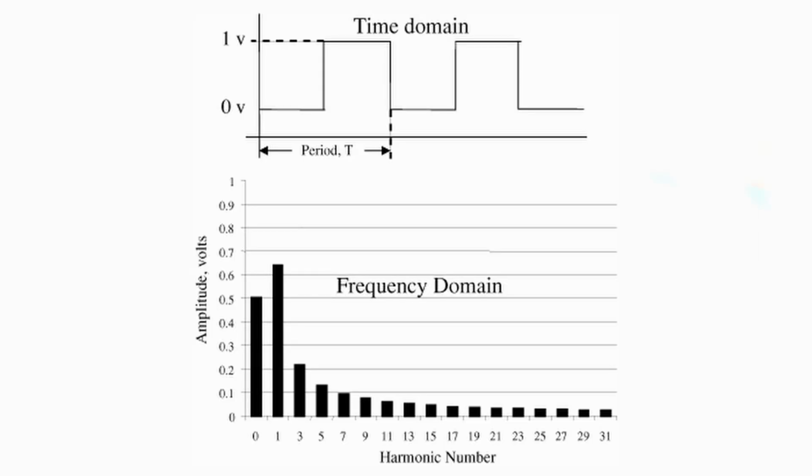Because remember when we talked about earlier that there is a significant relationship between the frequency of a digital signal and its EMI performance. Now, without going too deep into the Fourier series, the key takeaway that I want you to understand is that it will tell us the magnitude of the currents at each frequency across the spectrum. So imagine just a collection of sine waves, all with different magnitudes, and that is what we use to make up our periodic signals. This composition of sine waves can be thought of as the sort of noise profile of the periodic signal, and this will actually tell us what our radiated emission scans will look like.